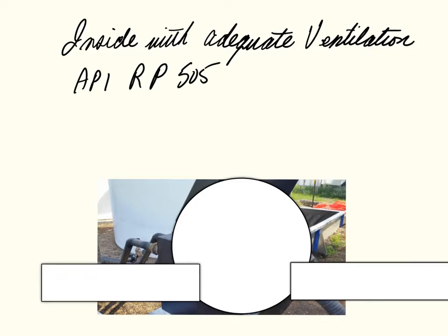And this is a document that's put out, I believe, by the Alberta Building Code or Canadian Building Code. And it talks about how much air, rather, has to be made available to break the concentration of hazardous gases down. And what the document essentially says is there has to be enough ventilation, if you're inside, to keep the gas-air mixture below the lower explosive limit, or lower flammable limit.